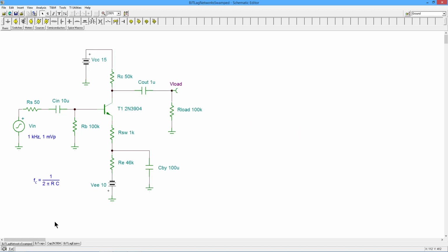Why? Because of the swamping resistor. C base emitter is here, but the Millerized capacitor actually goes from here to ground. So adding them together is not 100% accurate, but in all honesty, the Miller capacitor is generally a lot larger, and just sort of tossing in the base emitter capacitor, that'll put us really close. Okay, close enough for our purposes.